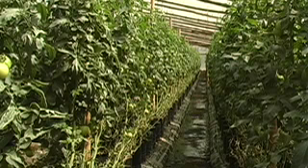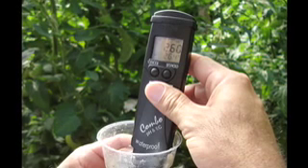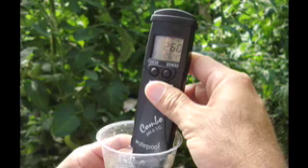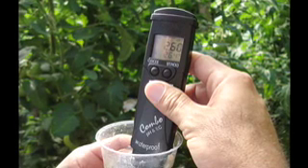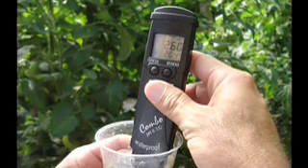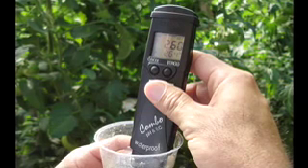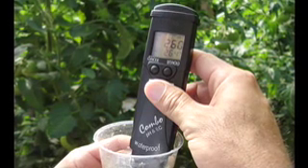To prevent salt accumulation in the growing medium, dilution rate adjustments or periodic flushing with clean water needs to be carried out. Electrical conductivity measurements, or EC measurements, of the leachate from the root zone will determine flushing needs. This leaching of the soil may be as frequent as once a week in areas with severe problems.